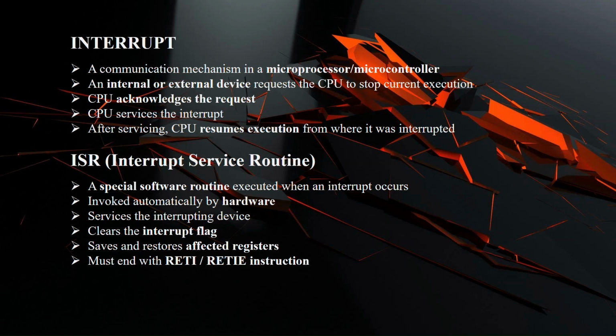ISR, which means interrupt service routine. An interrupt allows the microcontroller to respond immediately to an important event. When an interrupt occurs, the microcontroller pauses the main program and jumps to a special routine called the interrupt service routine.